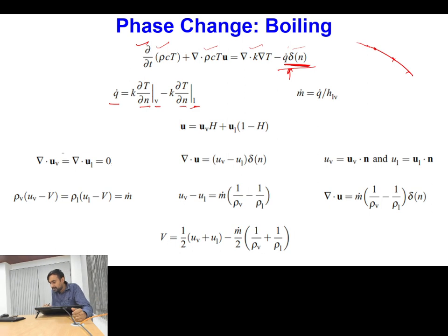So for the entire interface cells, you can simply explicitly specify the value of T equal to Ts at the given pressure. Okay, and on this side and this side you can compute the values of temperature from this particular equation. So using this equation on both sides of the interface you can compute temperature, and once you compute temperature, you will know the temperature in the neighboring cells.